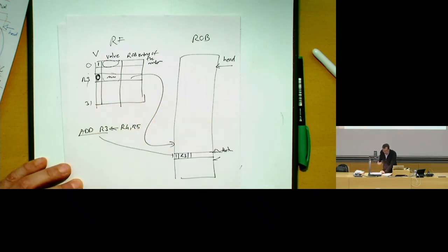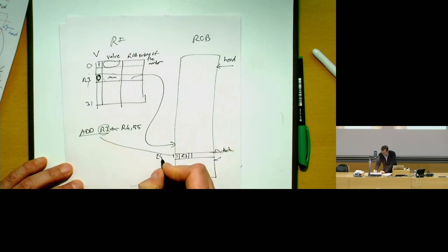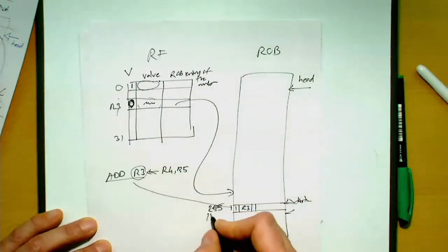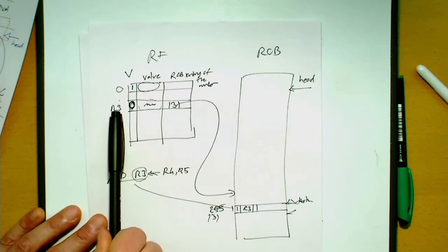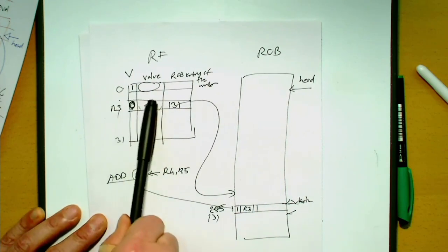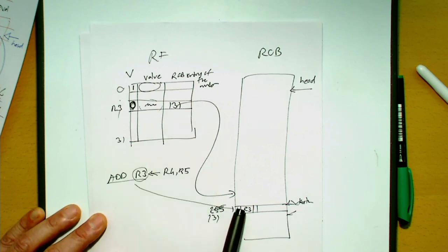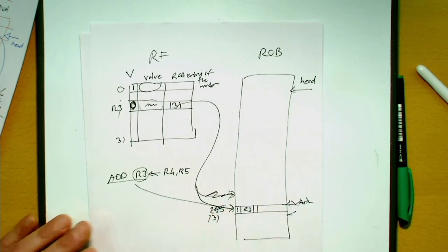For every later instruction, R3 is going to come from this instruction that's going to be in that location in the reorder buffer. And what is that location? I don't know, 255, let's say. Wherever that location is, basically, the tail pointer. I'll just make it 131. You basically put 131 over here. This means that register 3 is not in the register file. It's going to be produced by this instruction that's in reorder buffer entry 131. Make sense?